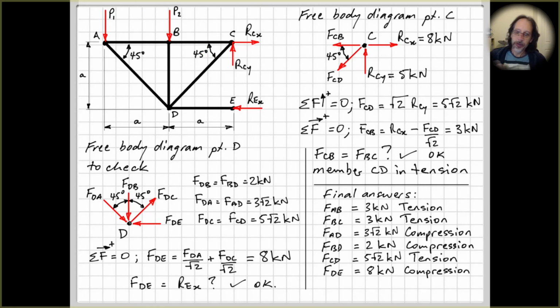Okay, so what you might like to do is to just note all of those where they're in tension and compression. Okay, so hopefully, you can kind of visualize members and whether they're in compression or tension, right? So, these forces are pushing down here and this is reacting in here, right? So this one's going to be in compression, pushing back against this force down here.